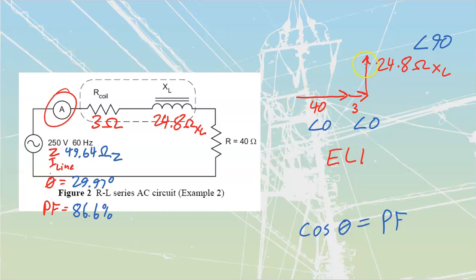Is what we've just done here accurate? Absolutely. It's the calculator that is doing all the math for us. We're putting it in, angle 0, and then we get that 24.8. And we know that we've got this 49.64 ohms. Really where they started to deviate was they went in with a 49.7 inside of their book that they had rounded to. So don't worry too much if you're a little bit off from what the book is. I prefer doing this because it gets me to these values immediately, and after that, once I've got those values, I can start working them back into other components.